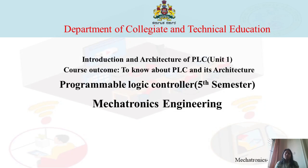Then after that, we have studied the advantages and disadvantages of PLC. Among the advantages of PLC, the first one is flexibility, then documentation, implementing and correcting errors, low cost, pilot running, visual observation, then speed of operation, etc. If we list some disadvantages, there are fixed program applications, that is, using the PLC for a single application is not efficient. Others are newer technology, environmental considerations, and fail-safe operations, etc.